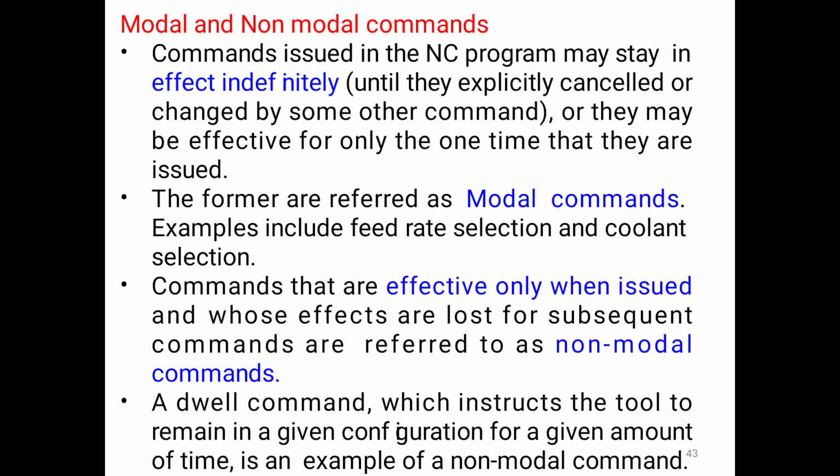Modal and non-modal commands. The commands issued in an NC program may stay in effect until they are explicitly cancelled or changed by some other command. Or they may be effective for only the one time that they are issued. The former are referred to as modal commands. Examples include feed rate selection and coolant selection.